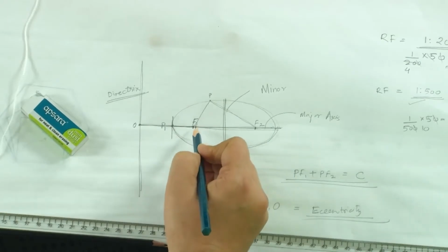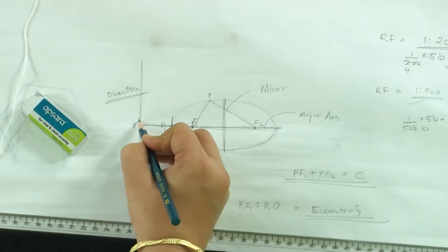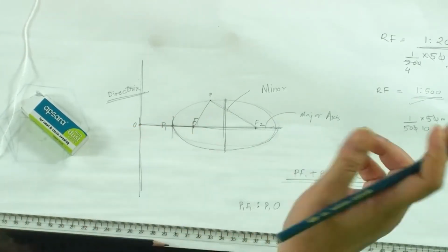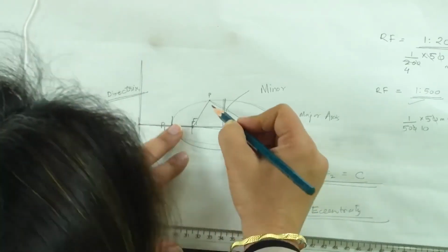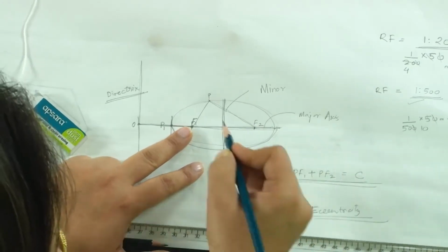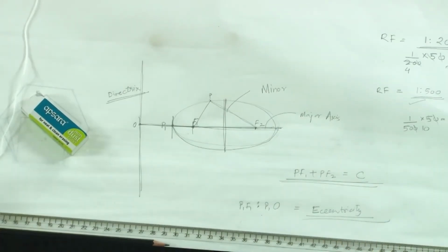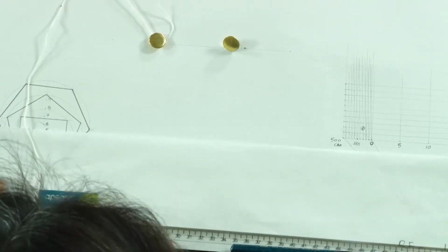So, we could either know the eccentricity and the distance of focal point from the directrix, either we get that, or we get this constant, that is the distance of the point from the two focal points of the ellipse plus the distance between the focal points. If we know either of the two conditions, we can actually draw the ellipse. Often we are given the directrix, the eccentricity and the distance of the focal point from the directrix. Often this is the condition that we are given. However, we would see how do we draw using both the given conditions.